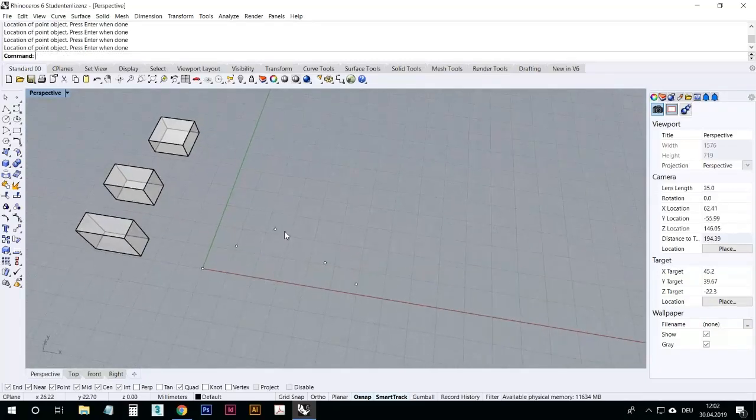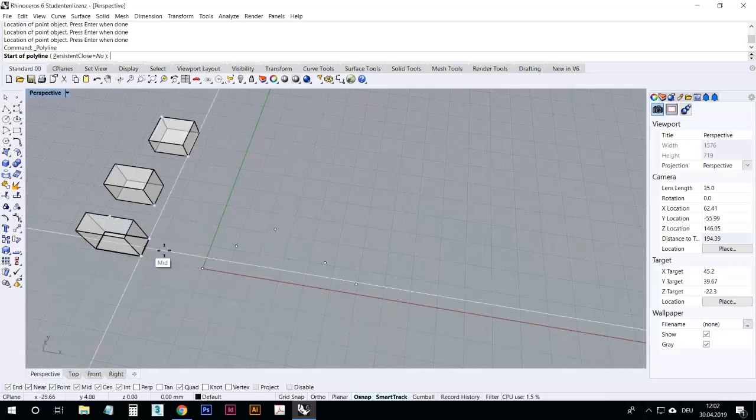Now we can have these as support points when you build something. So if you go to the next one, polyline, you might not have the snap system enabled. For example, end means that you find the end point of something, it snaps to it. So you know that you exactly hit that corner of the boxes that I'm showing now. Near would be anywhere on the side of it. Mid would be in the middle, for example. Point would be on a point. There are no points there, but here is a point, so you can snap to those.